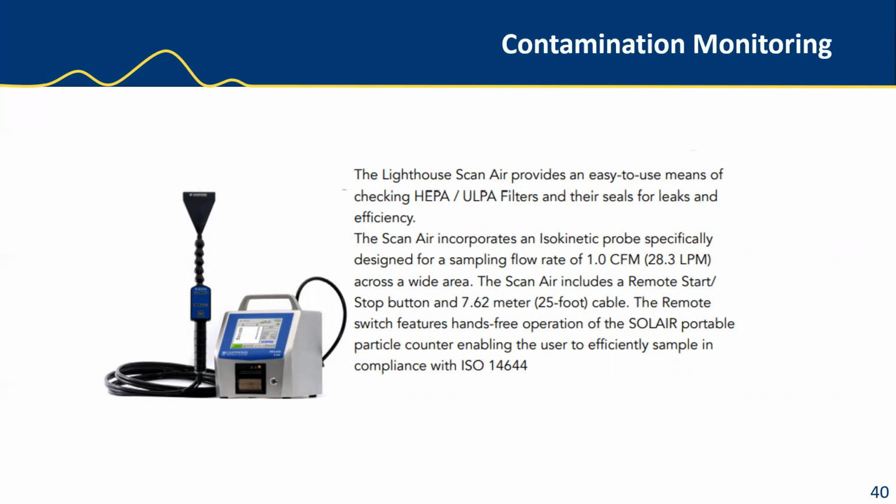Oil aerosols have been shown to clog up filters, and they are actually the ones they're testing. So that's one major advantage, as well as the higher resolution of a particle counter over a traditional photometer, which collects concentration data instead of sizing data. With the particle counters with the ScanAir Pro, you've got a system that will scan the filter face and give you more accuracy, and it will give you the actual sizing, not just the concentration level, so you get more resolution. And you're also using references instead of oils, so you're not going to clog up your filters with the process.